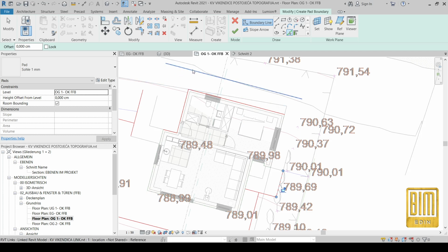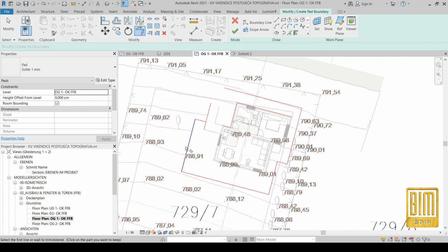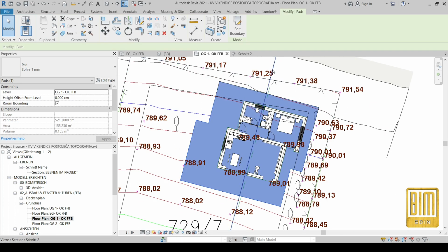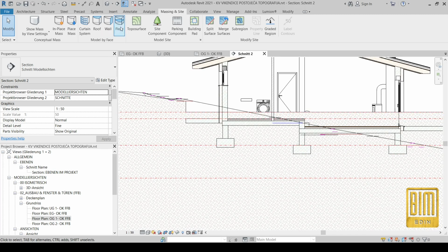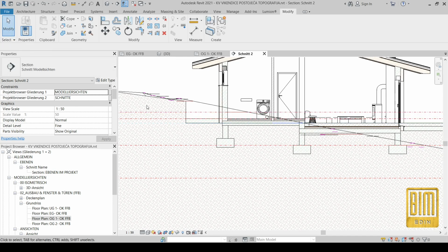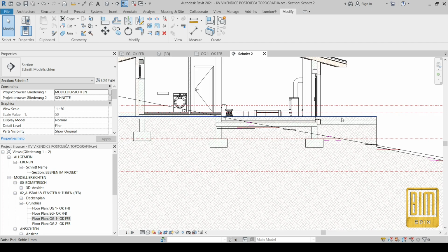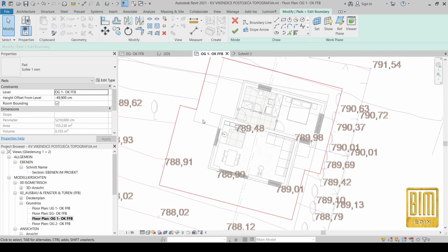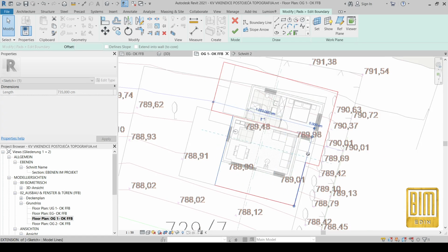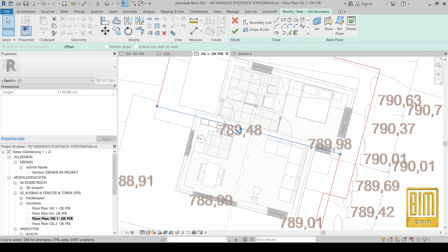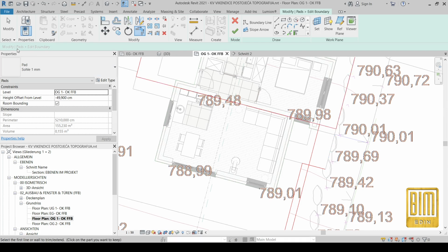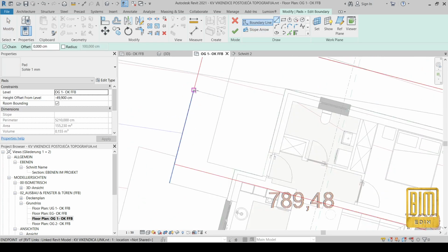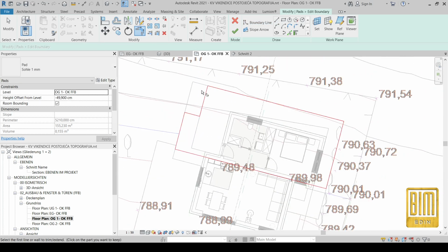All right, when I finish cutting, I will show you how to modify the topography to your new house. And now using a line tool, I will align this pad to the concrete slab. But our house, the ground floor, is not on the same level. We have here two different levels with a 35 centimeter difference. So I will separate the pads in two. First I will model the upper level, and then I will model the lower level.